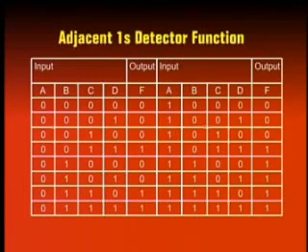Now, how many AND gates are required? Basically, 8 gates are required to implement the 8 minterms. As you can see from the function table, the output F is set to 1 for 8 different minterms. So, 8 AND gates are required to implement the 8 product terms.